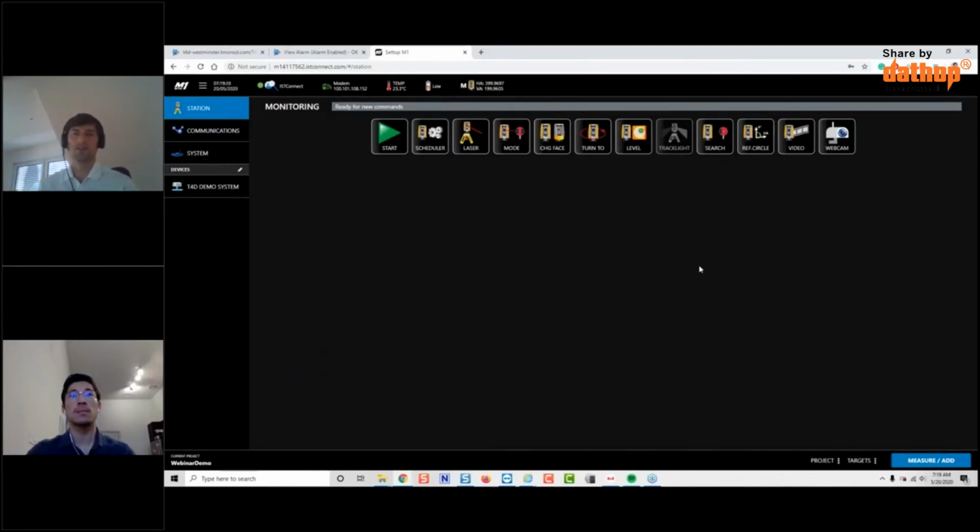You can also add multiple GNSS receivers, and we have real-time GNSS engines in T4D and also post-processing engines. So yes, you can connect all of them, and you also get the displacements in 3D, the height component, for example. There are different settings, baseline mode, VRS mode, but this is too detailed now. So the short answer is yes, this is supported.